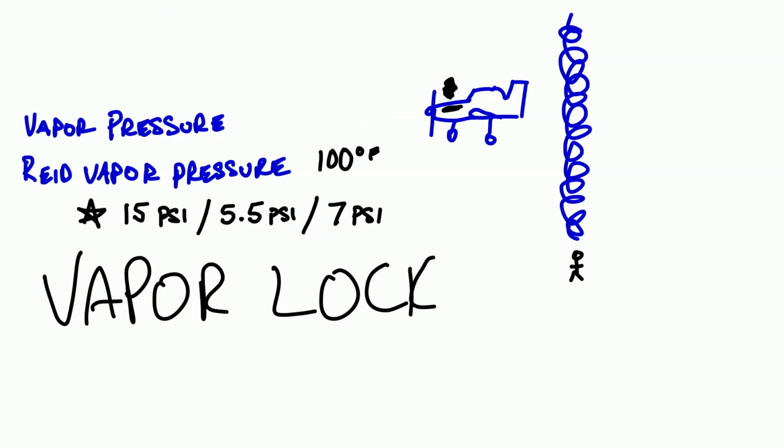And vapor lock is effectively when we form a gaseous form of fuel within the lines that are running through the system. And as we know, most pumps are going to work a whole lot better at pumping liquid gas than they are at pumping vaporized gas. So it can create effectively a block in the system. It can actually cut off fuel flow to the engine and stop the engine in flight, or it can make it very, very difficult to start the engine once it's on the ground.